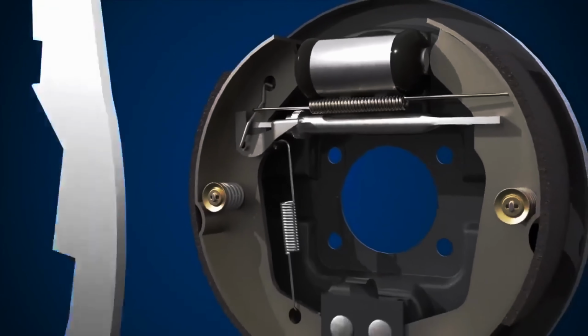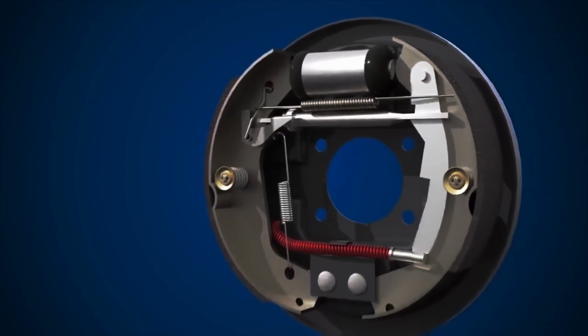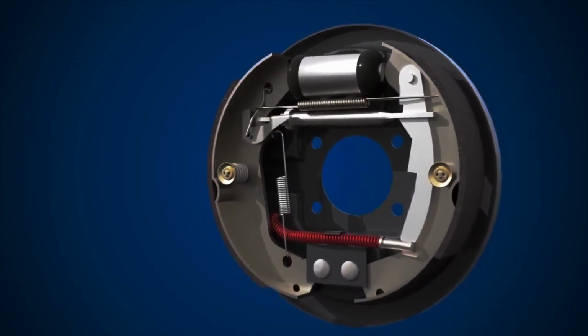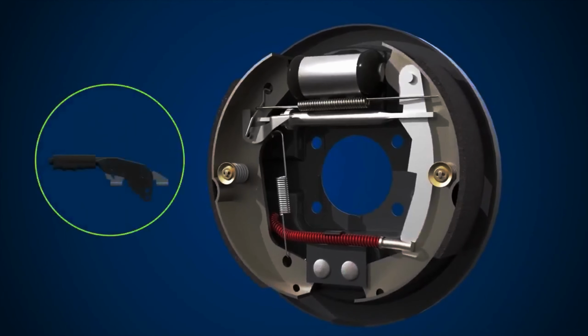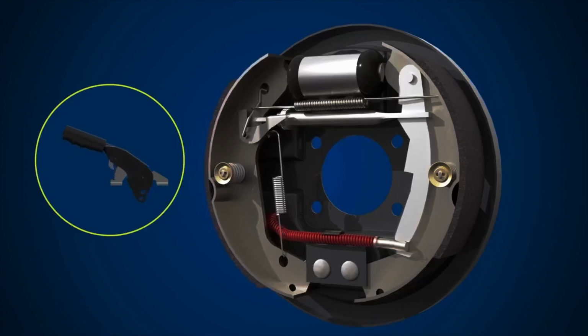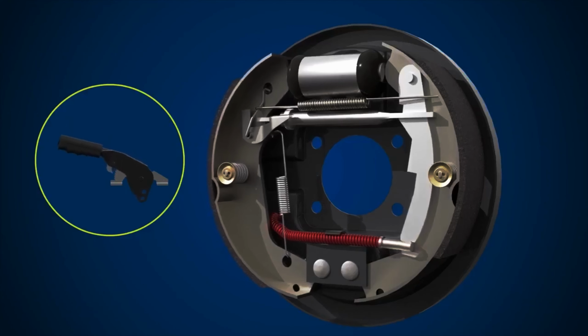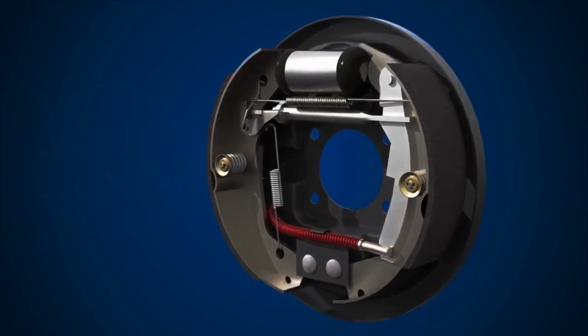Finally, we have the handbrake mechanism. The handbrake cable enters the drum through the back plate and connects to the brake shoe lever arm. Cable, electronic, and hydraulic systems are found in handbrakes, but in our example, cables are used to activate the rear brakes. When the handbrake is pulled upwards, the cable is tensioned, forcing the brake shoes out against the brake drum. A ratchet in the handbrake maintains this tension until the handbrake is released. And that's the basics of a drum brake system.